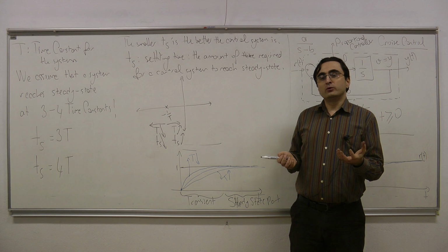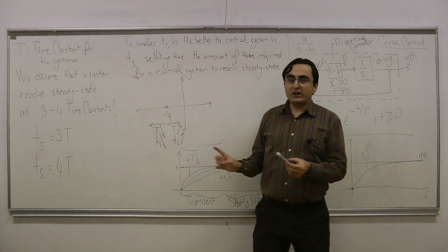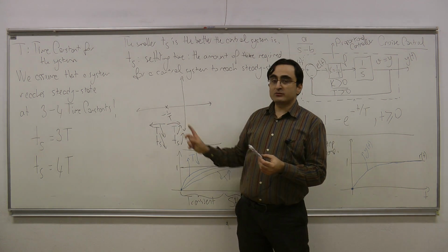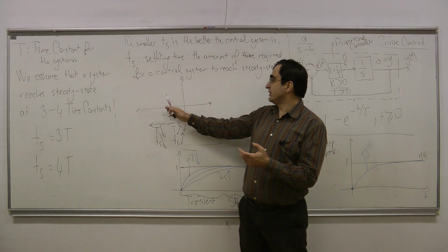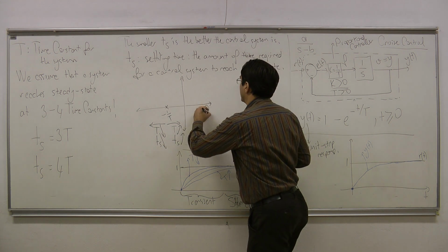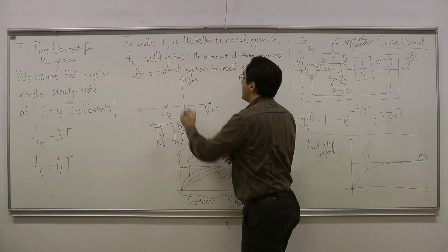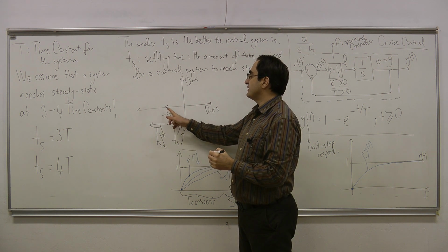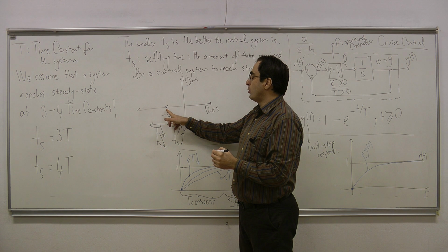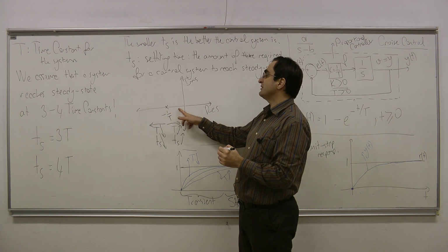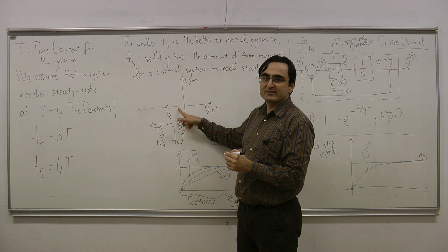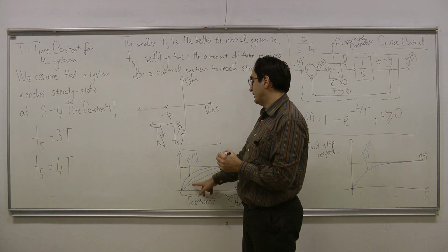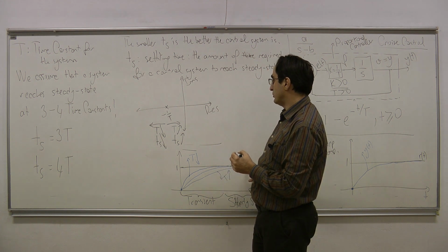So this is the aim of time domain analysis. What are we doing here? Pole location is a Laplace domain quantity, which we can see on this pole zero plot. And by looking at this pole location, we can say that if the pole location comes towards the right, if it approaches the imaginary axis, then the control system becomes slower. I would have a slower response.